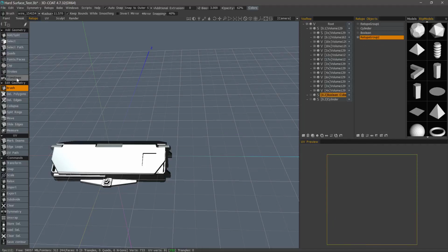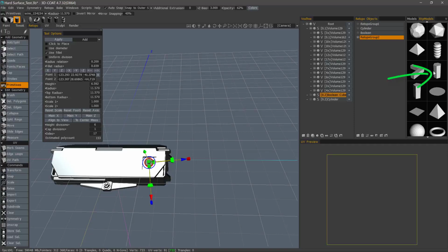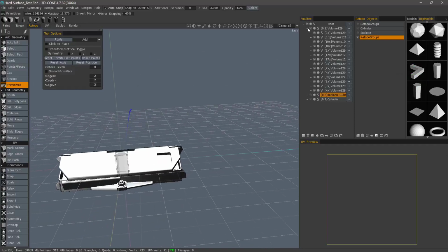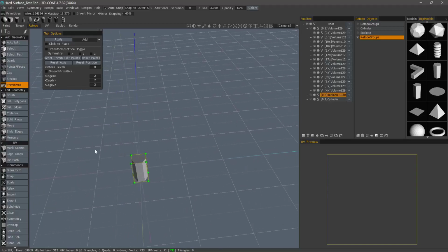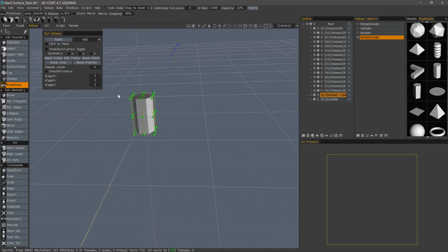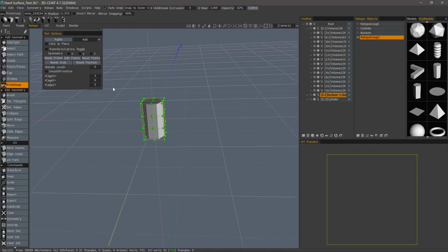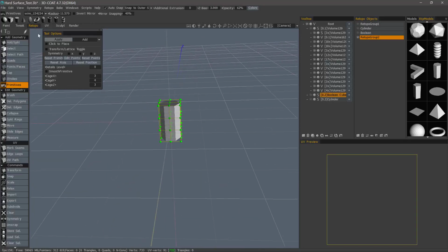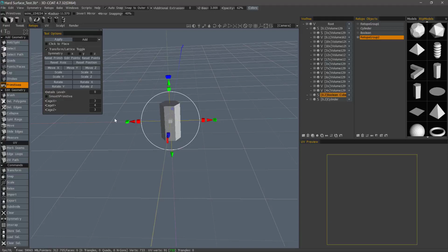And now I will select the primitives tool and select this object. I'll temporarily hide the underlying voxel object. You can see it has this lattice around it, so we can change the control points arbitrarily, just like we could in a sculpt workspace. So let's make that 4. We can use a freeform lasso to select all the points, and now we have a standard transform gizmo. Another option, if we want to transform just the entire object, is we can check the transform lattice toggle.